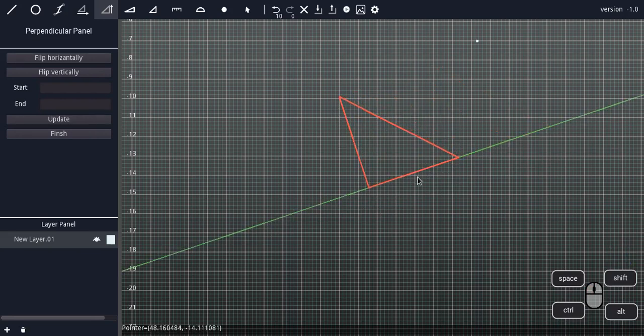The red line represents the ruler direction. And here you can see two input. Let's set the first one equal to 1. It will draw a dot 1 unit away from the green line in the direction of the ruler. Let's make the second input equal to 3. Now it will draw a line that starts from 1 unit and ends at 3 units. So when you're specifying one input only, it will draw a dot. And when you're specifying 2 inputs, it will draw a line.